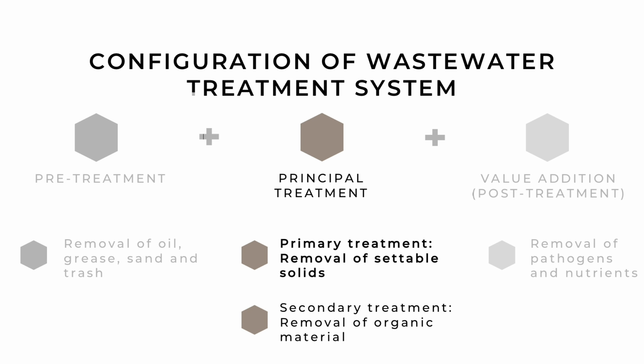As I said before, the principal treatment in wastewater technology is divided in 2: primary treatment and secondary treatment. Within the primary treatment, suspended solids are removed thanks to physical processes. Much of the suspended solids are organic matter in suspension, which means that their removal in a simple sedimentation tank implies a reduction in the BOD load that arrives in the secondary treatment, which is usually more expensive.